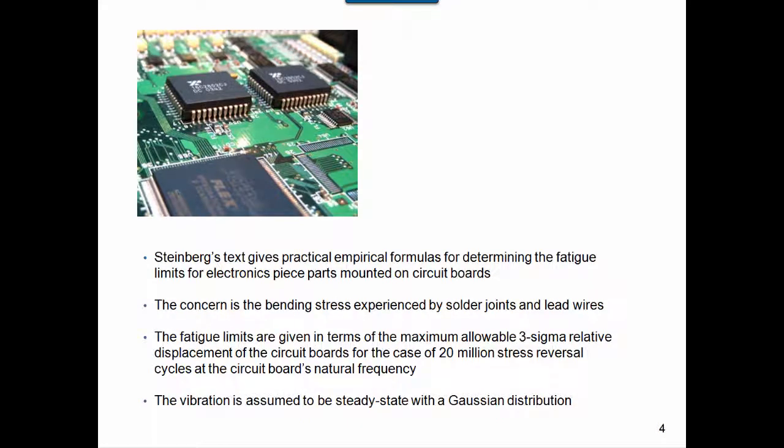So here's a circuit board, and our concern, and this comes from Steinberg's work, is that those lead wires and solder joints are going to fail, that those are the weak links. And the circuit boards themselves are going to be undergoing bending vibration. Now, if you want to get into all the theory, there's also torsional vibration modes and membrane modes and longitudinal modes and all sorts of other vibration modes. And we can even start talking about wave behavior. But the driver is going to be the bending modes, and more particularly the fundamental bending mode of the circuit board. That is what's going to induce most of the stress into those lead wires and also the solder joints.